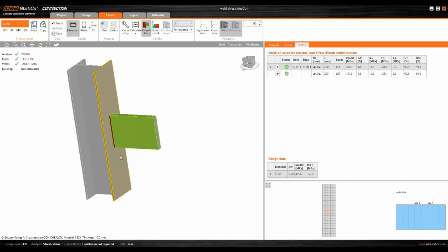So I think, Adam, it's usually that you have to disconnect all entities, right? Am I right? Yes. Usually you have some objects in AutoCAD, so please try to disconnect to really simple. Yes, explode. If you want to import in DXF, it has to be in the most simple form of it.